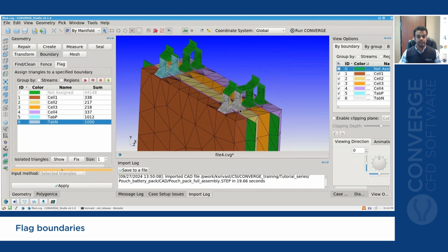So this is our parallel connection. And then for a serial connection, the negative tabs connect to the positive tabs for the adjacent pair. I'll go back to positive, and then these 2 act as the negative tab for those pairs.